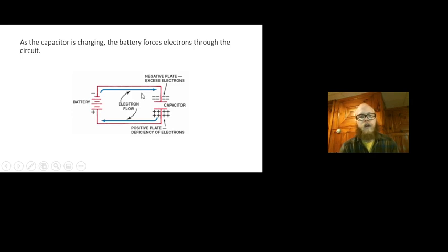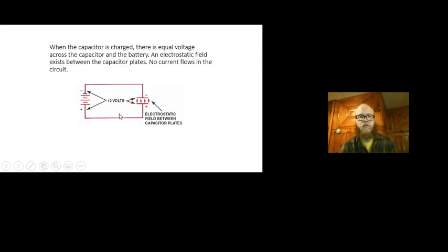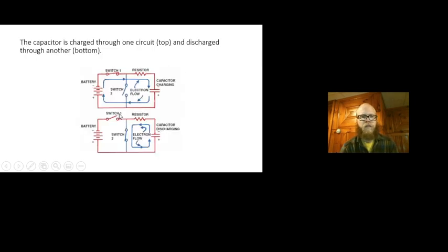And then when we disconnect the battery, the current all tries to go back into the battery again or through a load. And I've got a slide there. So we'd charge up the capacitor this way. Usually you want some sort of a resistor there because the capacitor can really soak up a lot of current really quickly and let it out really quickly as well.